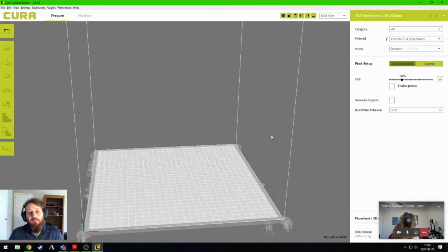I've had to replace the bed on it. Well, it was semi-optional, semi-not. The bed that comes with the Ender 3 is like a plastic type of bed almost. So it bends and warps easily, so I replaced it with a glass bed. It's a good upgrade. Definitely worth it, because the main issue I was having when I first got it was that certain prints weren't sticking. So it would get halfway through the print and I would leave and go do something, and when I came back, it would just be this glop of a mess on the bed, and I'm like, what happened?